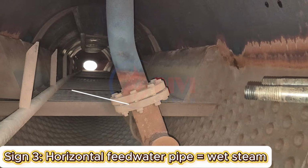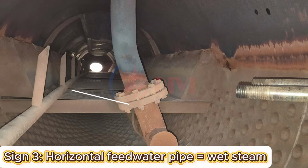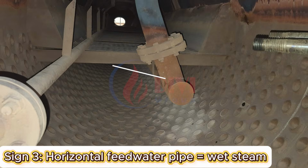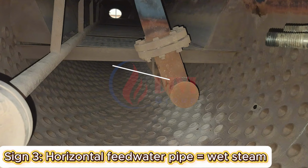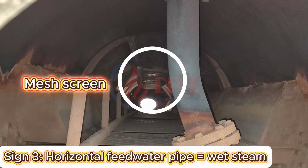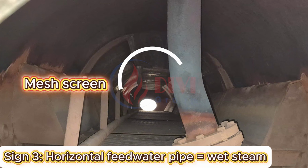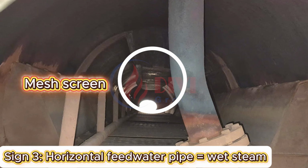Third sign, when opening the steam drum, if you see the feedwater pipe lying horizontally at the waterline, not separated from the rising steam flow, that is solid evidence you're using wet steam. Some companies thought that simply installing a mesh screen at the steam outlet would solve the problem. But in reality, this is only temporary and not an effective solution.